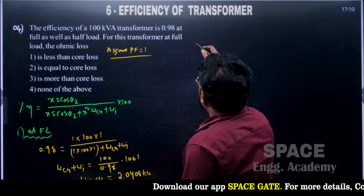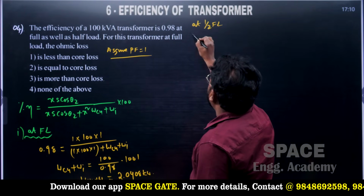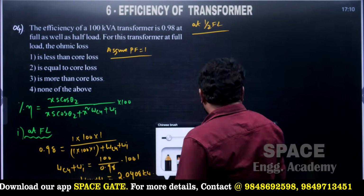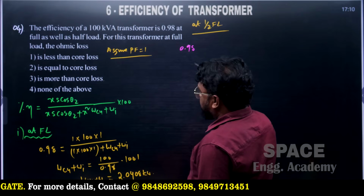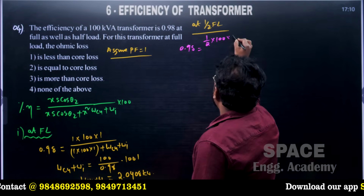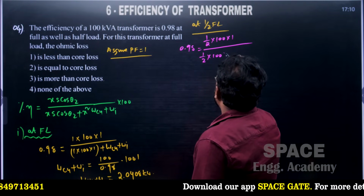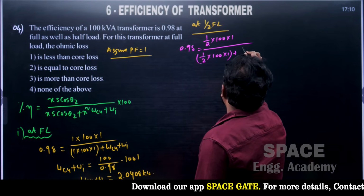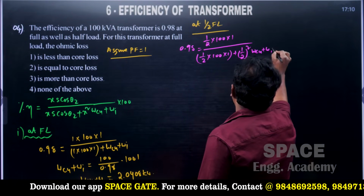And next, similarly, at half full load condition, what is the efficiency? At half load it is also the same efficiency, 0.98. Half load means x equals 1 by 2, so 0.98 equals 1 by 2 into 100 into 1 divided by 1 by 2 into 100 into 1 plus 1 by 2 whole square copper losses plus iron losses.